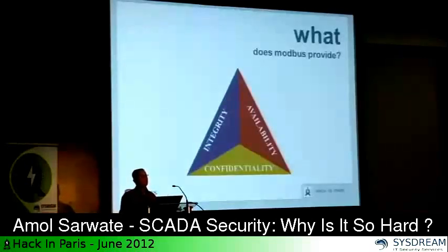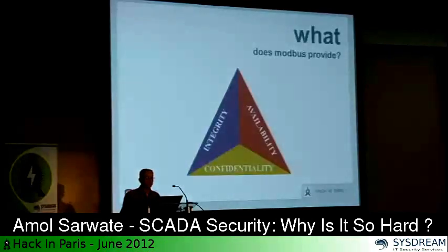In DNP3, you could say, okay, give me the temperature or pressure or whatever, only if it has changed. Otherwise, I'll assume it was what it was earlier. In DNP3, the client can register that, hey, whenever the temperature or pressure or whatever changes, notify me. So the server can automatically notify that a temperature or pressure has changed. So a little bit more advanced than Modbus.